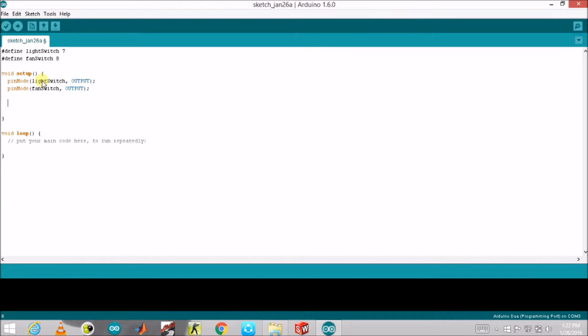And now here we initialize our serial communication. If you don't know about serial communication in Arduino, then I suggest that you refer to the Arduino documentation and see some other tutorials based on Arduino. Basically, I'm going to initialize the serial port by saying this statement: Serial.begin, and it takes in a parameter, 9600, an integer value. Serial.begin essentially initializes the serial communication between the Arduino and the Bluetooth module at the rate of 9600 baud per second. And here our main code starts.